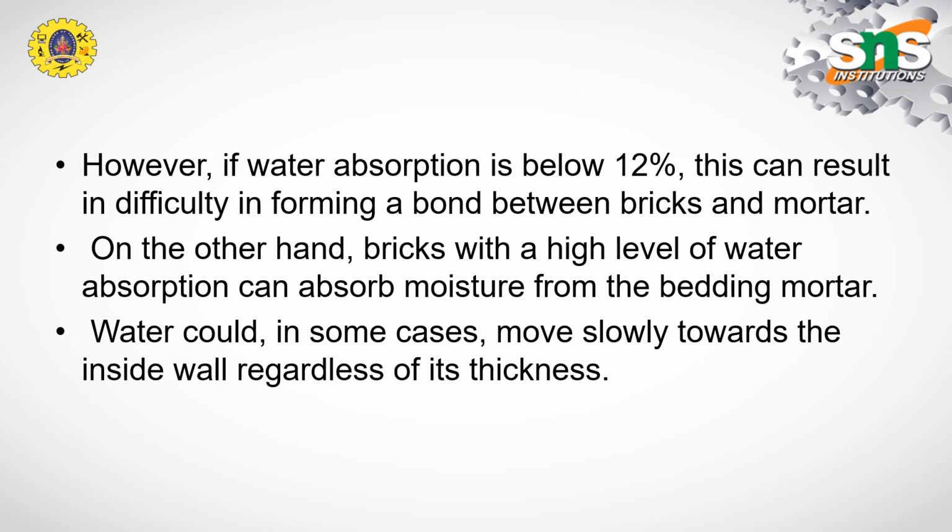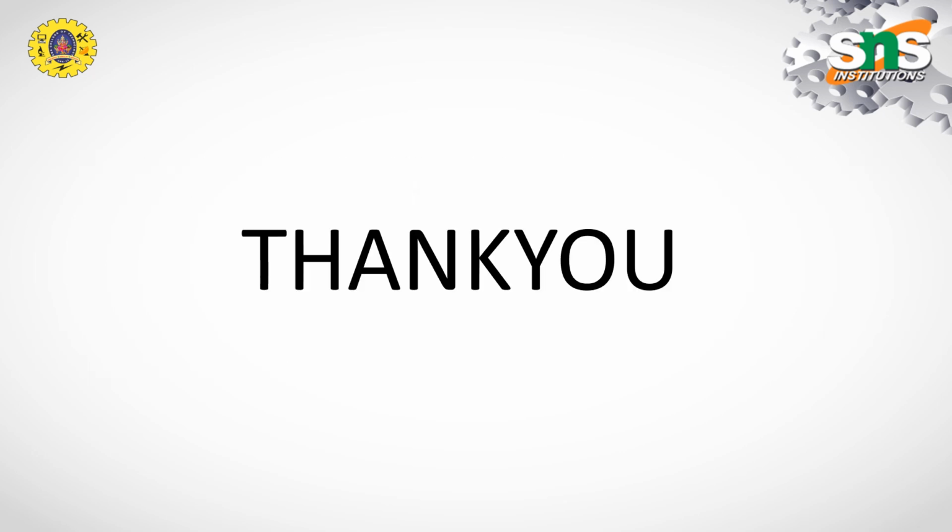Absorption is nothing but water getting penetrated into the brick's material all over its thickness. That is the absorption property. More than 25 percent is not good, and below 12 percent is also not good.